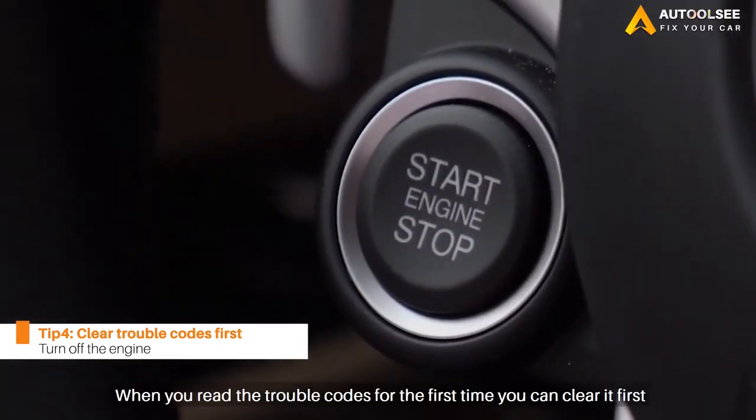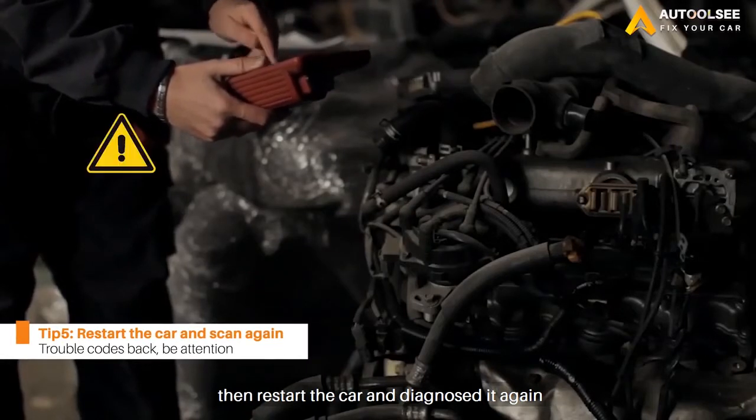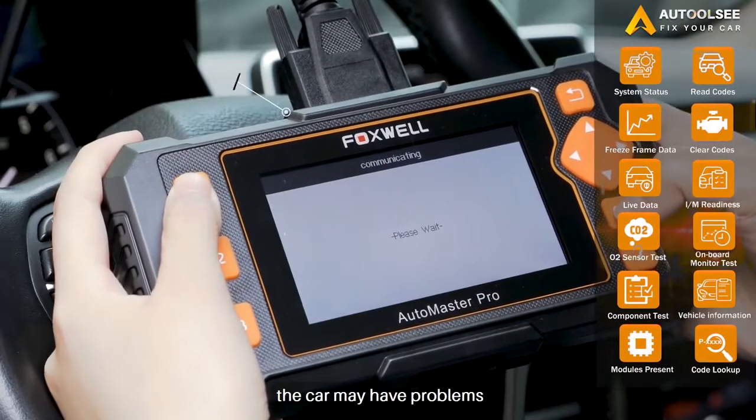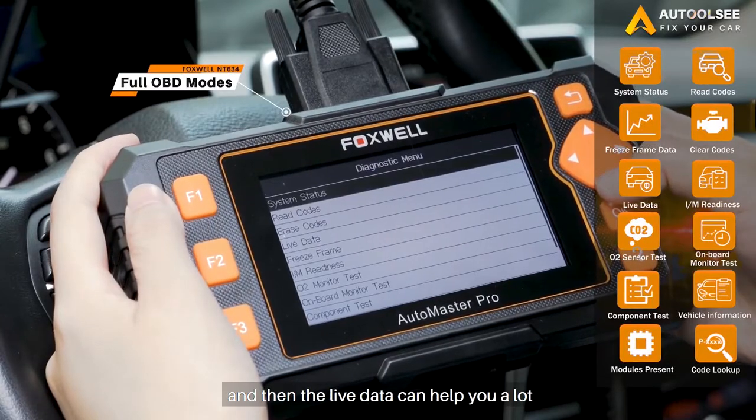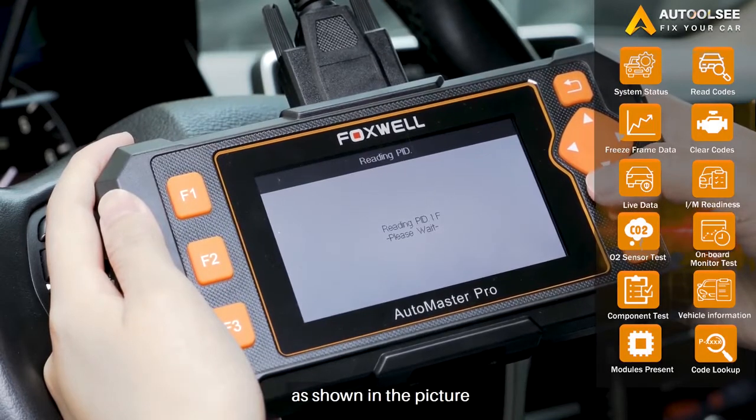When you read the trouble codes for the first time, you can clear them, then restart the car and diagnose it again. If the codes come back, the car may have problems. And then the live data can help you a lot. Of course, this tool also supports 10 OBD modes, as shown in the picture.